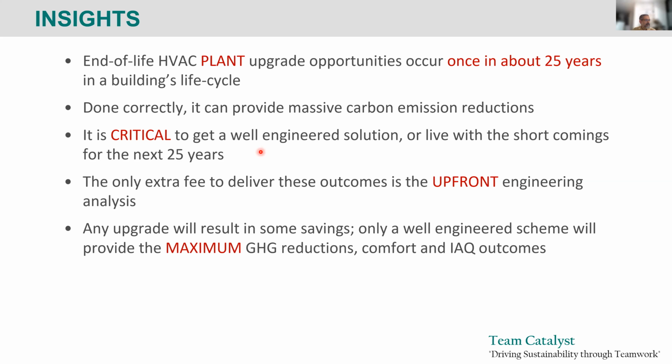If you're able to do a facade upgrade, your facade, particularly your glazing, can be enormously more efficient than the original. You really must do a rerun of the sizing and then work out what is the best outcome. In our case, we looked at the weather. We knew it was a humid place, and therefore we then thought about what needs to be done.